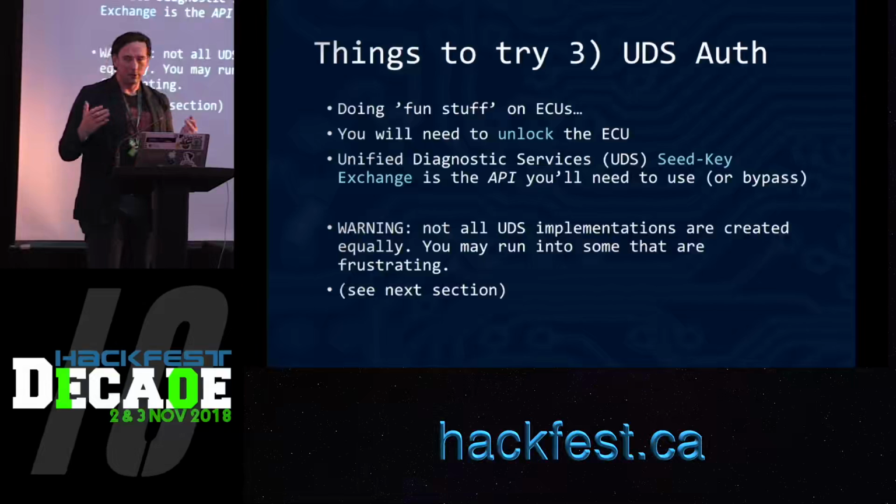Okay. So our plan, again, if you're going to reverse an arbitrary firmware someone gave you to get some information out of it, you're going to have to go through these steps. And I'm marking in blue the stuff that we're not going to do in this talk because then the talk would be too long. Also the stuff in blue is from a different talk, so you can go back to that prior art in BSMT's blog. But I am going to talk about the stuff in yellow. So you're going to get that firmware. You're going to figure out what architecture it is. You want to figure out where it's loaded, what's that offset. And then actually get that in the right offset. You want to go and find loader loops.